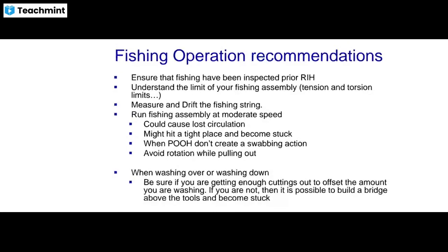Fishing operation recommendation number one: ensure that fishing tools have been inspected pre-well. You have to understand the limits of your fishing assembly, tension and torsion limits, and measure and drift the fishing string. Run the fishing assembly at moderate speed; otherwise it could cause lost circulation, or might hit a tight place and become stuck again.